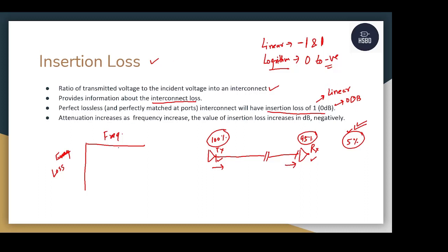As soon as the frequency increases, the attenuation also increases in the transmission line, right? It's because of the losses of the copper as well as the dielectric. The copper losses and the dielectric losses play a major role here. If you have a copper loss or a dielectric loss at a higher value, then there are chances, or there are speculations, that if your insertion loss is very high, these might be the reasons behind it. So we call them the materialistic losses.